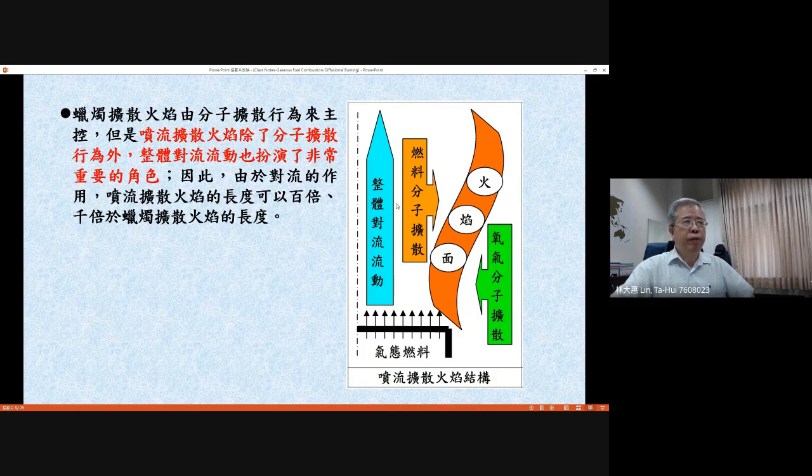But for the jet flow, there is an overall convective flow coming out, and it will push the gaseous molecules to move very fast further downstream. This supply of gaseous fuel means a large amount of heat may be released from the flame, but in the structure you can have a backflow moving around the flame position.